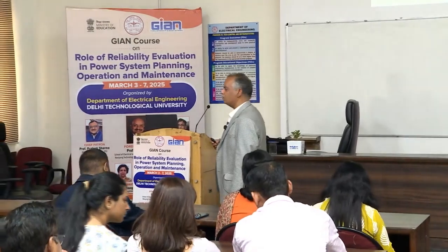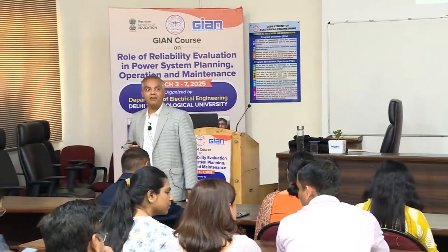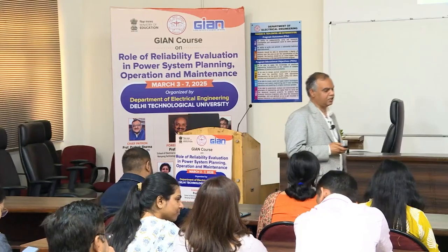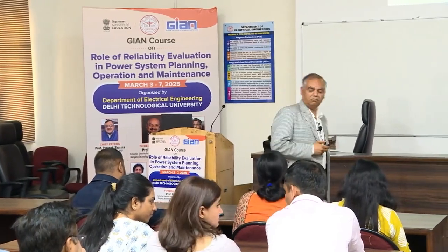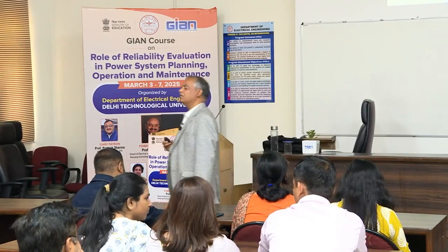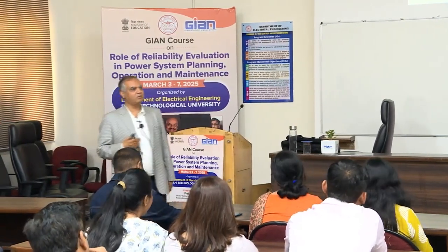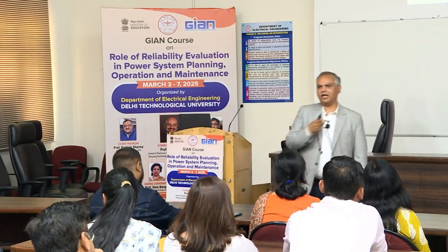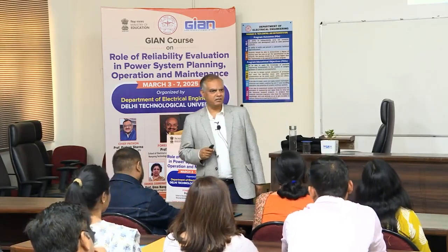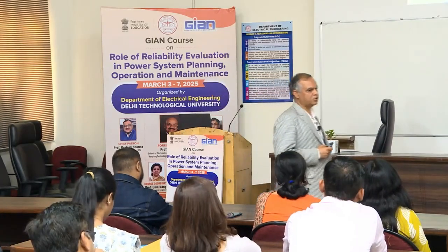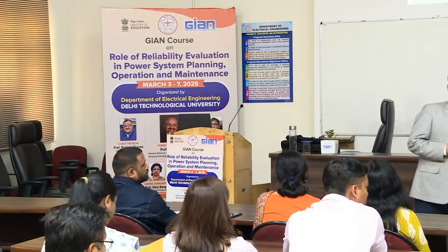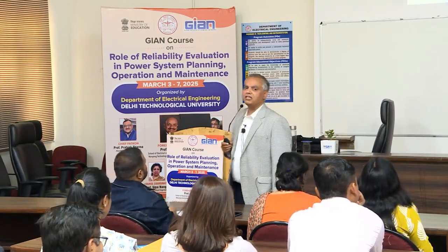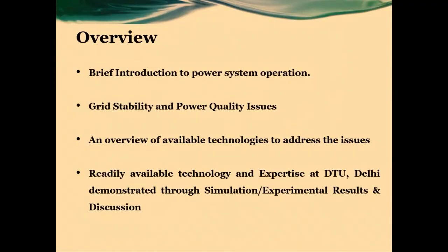What is their impact on grid stability, reliability, and efficiency also. So as you know, most of the time our conventional generation is very... In conventional generation there is only one way flow of power, right, from generator, then transmission, and then discom. But as you know, more and more renewable energy sources are coming into the picture, so bidirectional power flow is also possible, and not only bidirectional power flow, with the penetration level the inertia is also being compromised, because the inertia has